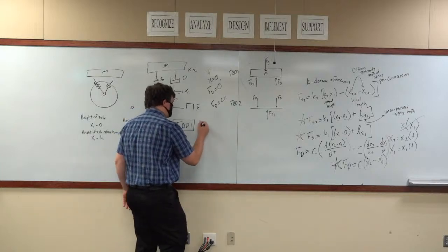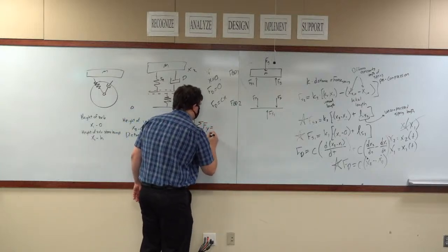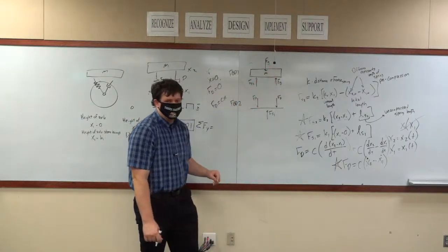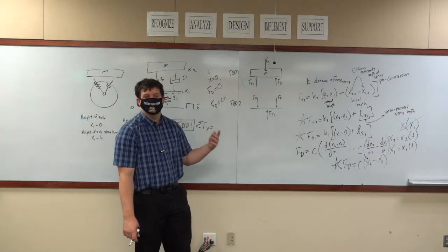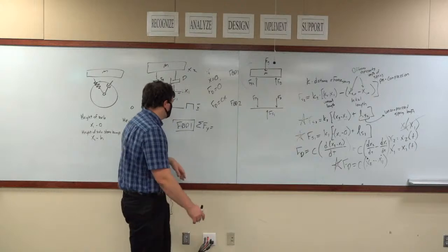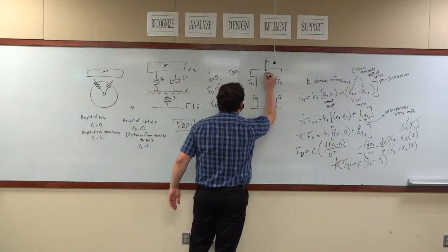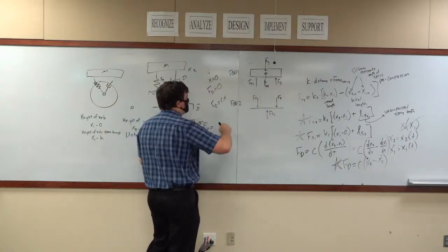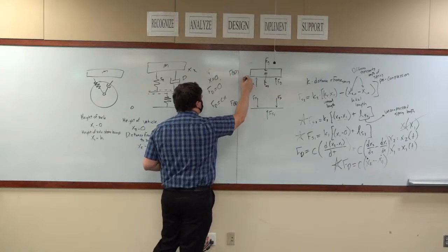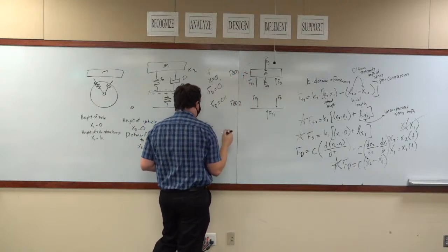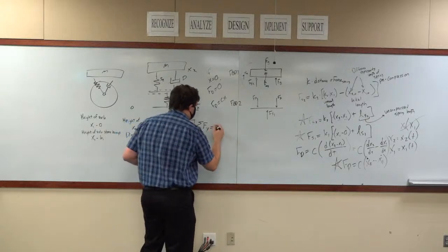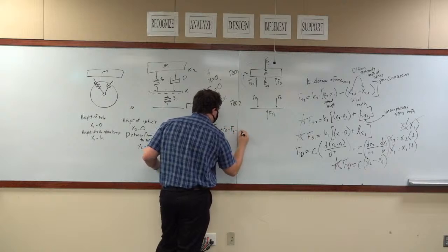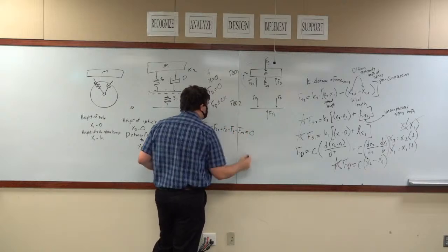So from the first free body diagram, the sum of the forces in the y direction are equal to, we have three forces, but we're also going to include a fourth force, which is the inertial force, because otherwise it's equal to ma. So we'll take this FMA, and we'll say this direction is upward for y, and then what we have is FS2 plus FD minus FG minus FMA is equal to 0.